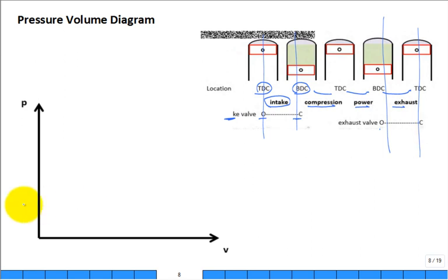First of all, put in right here 1 atm. Why? That's the air pressure outside your engine. The air pressure in this room or wherever the engine's operating. And what happens during that intake stroke, think about it, we're going to plot the pressure of the gases in the cylinder. That's the gas in this cylinder right here.